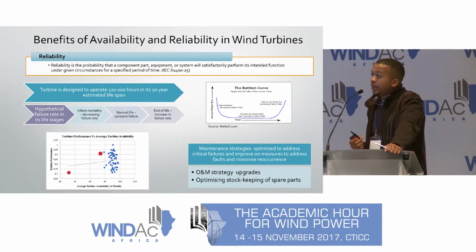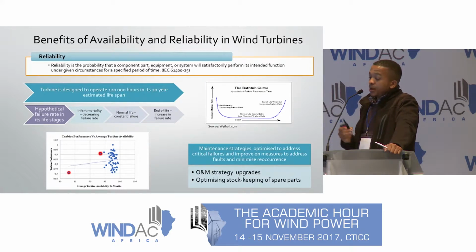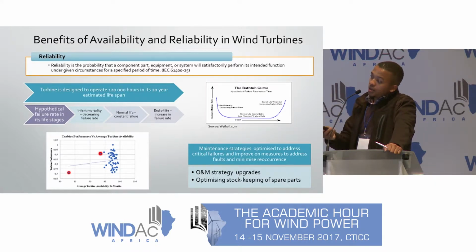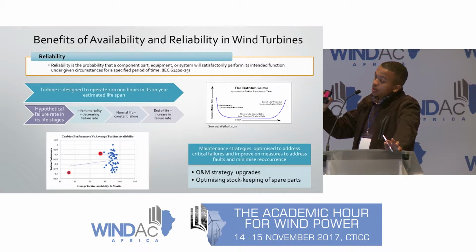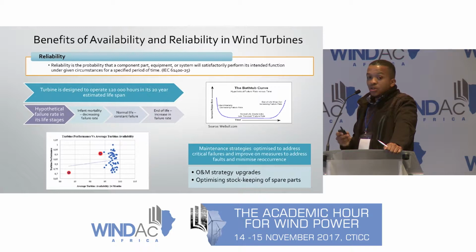Another problem I'd like to highlight with simply studying wind turbine availability, without considering the wind turbine components, is shown in the image on the bottom right. The scatter plot indicates the wind turbines' availability throughout the 24-month study period, and this shows that when the average availability is taken for all the 60 wind turbines considered, you would find that these wind turbines meet their expected availability.